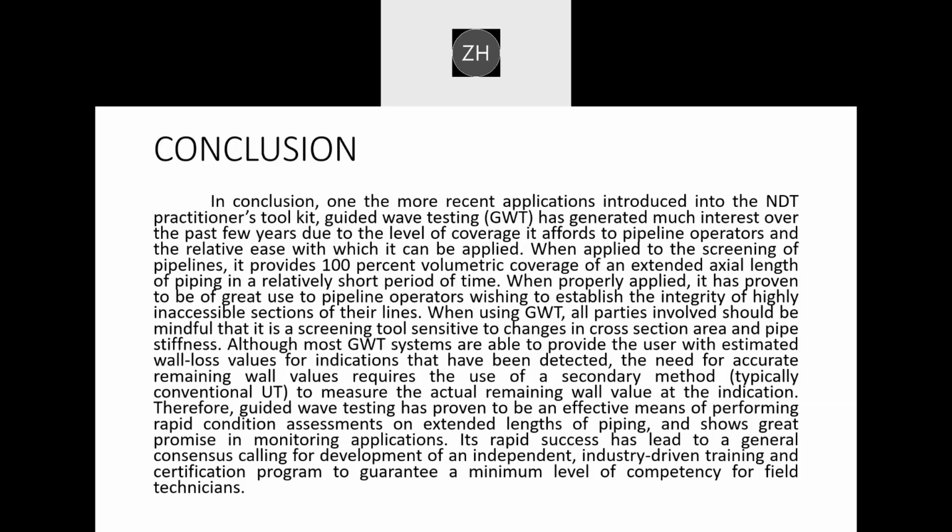When properly applied, it has proven to be of great use to pipeline operators wishing to establish the integrity of highly inaccessible sections of their lines. When using GWT, all parties involved should be mindful that it is a screening tool sensitive to changes in cross-section area and pipe stiffness.